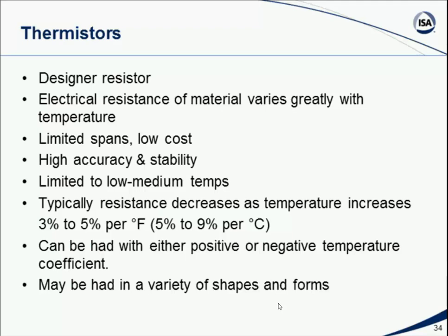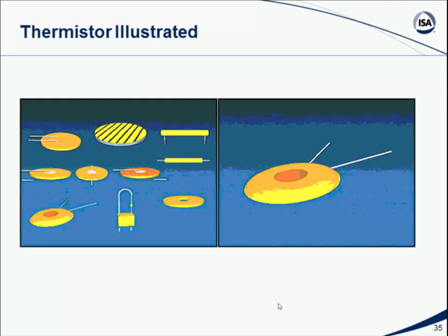In fact, thermistors are quite often embedded in electrical circuitry. If you ever wonder how your computer, for example, knows that the circuit card inside the memory card or the processor card is getting too hot, well, that's probably because it's got a thermistor mounted on it somewhere in some circuit that's measuring its resistance to make a temperature determination. Again, thermistors are manufactured in a variety of shapes and sizes. They're usually glued to devices. And again, they can be very, very tiny. They can be the size of a small, not quite pinhead, but a tiny little bead.